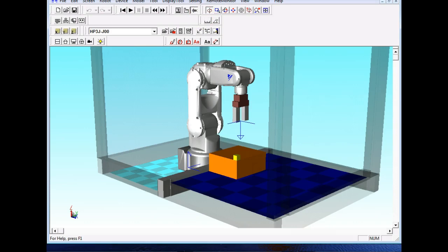And we had two categories of methods of programming industrial robots. We have what's referred to as continuous path, and then we have what we call point-to-point. By far, the most widely used is point-to-point, because it's got quite a few more advantages. Some, it's easy to program, and next, the programs are easy to edit.